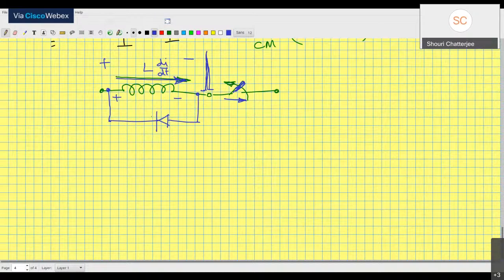But when you throw open this switch and this voltage builds up, this diode is going to start conducting and take away the current before the air gap across the switch ionizes. This is where you use a freewheeling diode. This is its responsibility: its job is to carry this current through.